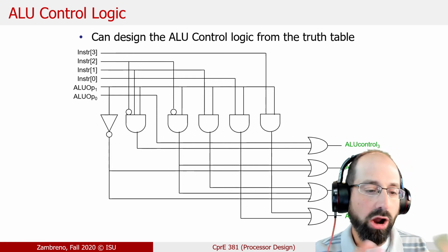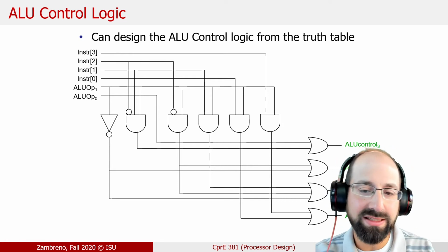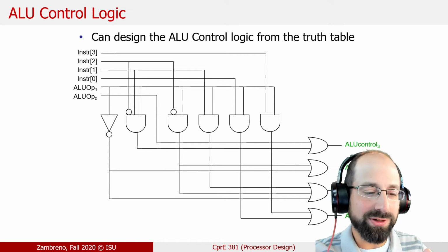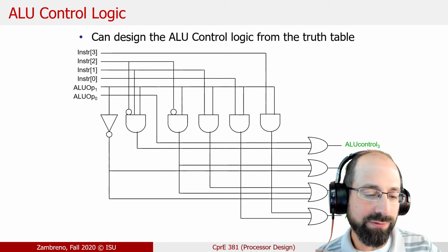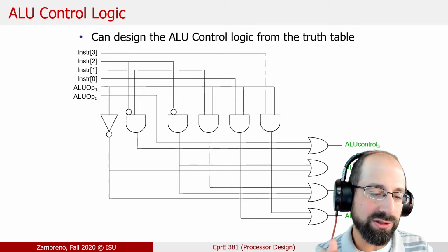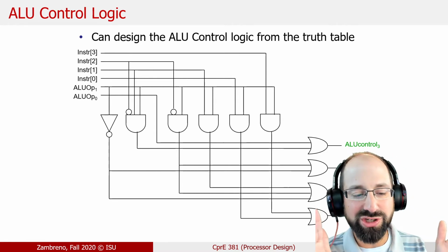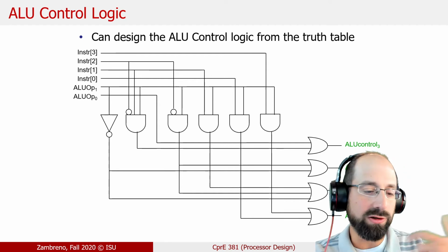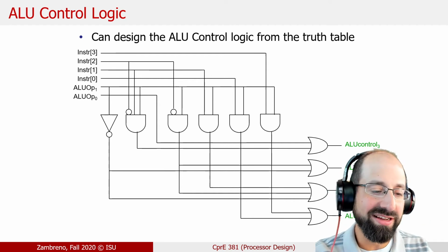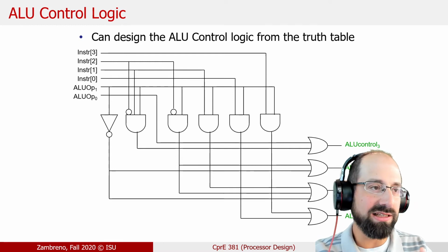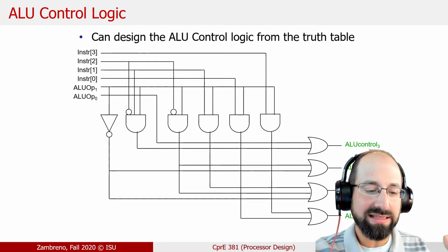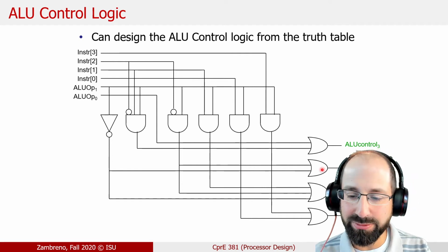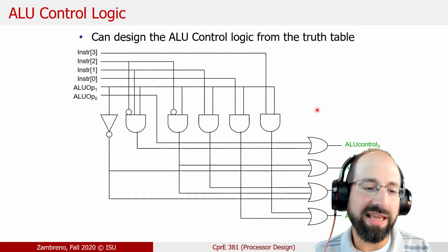Our approach is the spreadsheet approach, which is opcodes and function codes as the rows of our spreadsheet, all the different encodings we have to support for our instructions, and all the control signals we want to generate, including the control signals that dictate whether it's an add or a subtract or an OR operation. Treat it as a large switch statement or case select statement in our VHDL, and then let the synthesis tools take care of that for us.